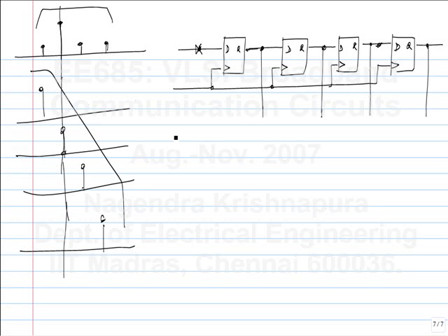Let's say I have voltages V1, V2, V3, V4, and I want to get a weighted sum. Summing digital to analog converter, summing integrator. What is the principle behind the summing integrator? So in general, when you want to add, it's easiest to add currents. Generally, why is it? Why is it easier to add currents and not voltages?